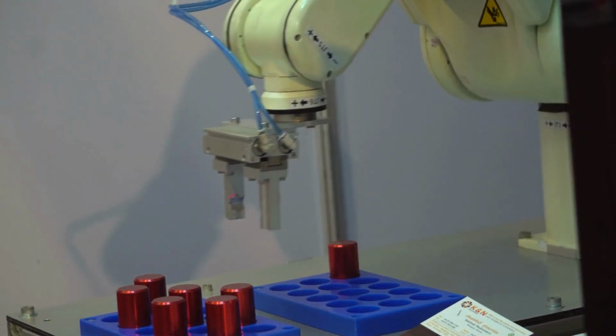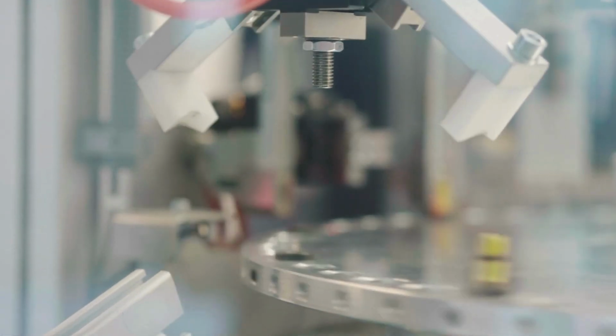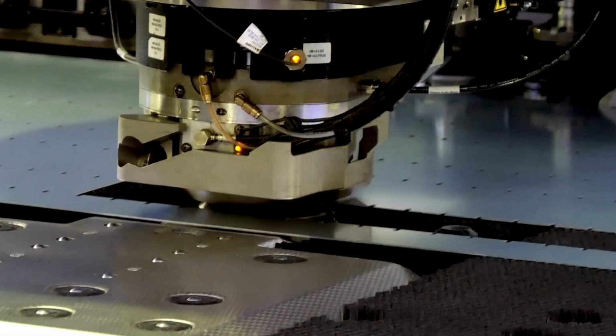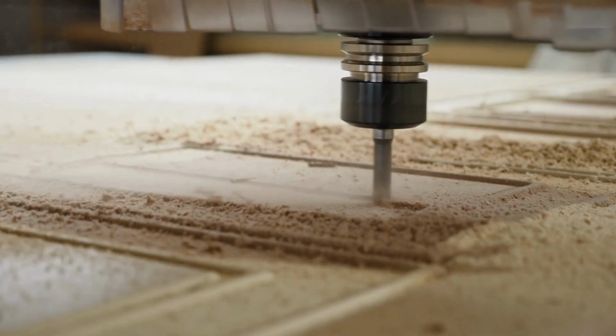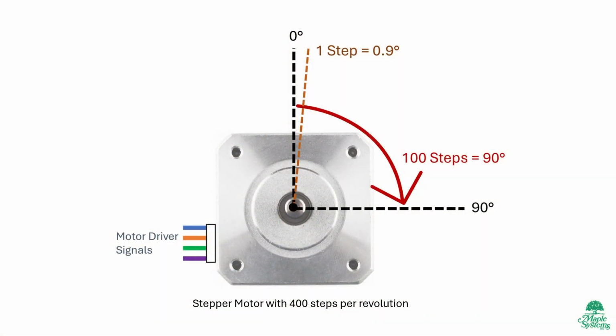The use of positioning is for precision. Generally, it refers to rotating a motor at an incremental amount to achieve a desired position. A good example of this is in a CNC machine where the spindle needs to move 6 inches. We can send a certain amount of pulses to the motor to interpret the rotational movement of the motor to a linear distance. Now, you may be wondering, how do the pulse outputs translate into motor rotation?